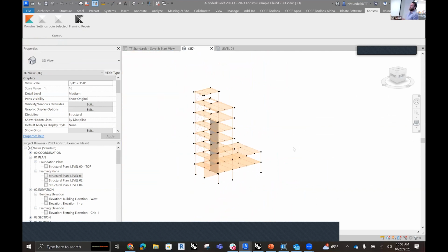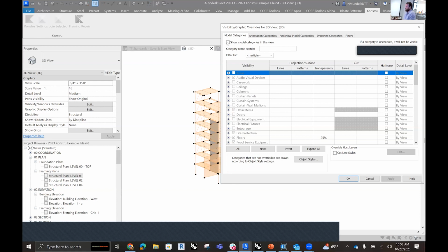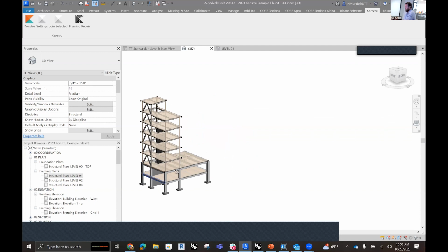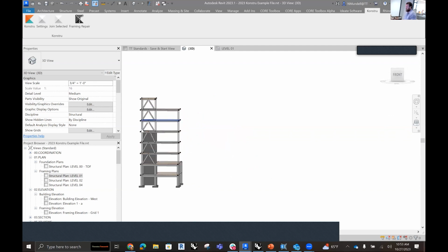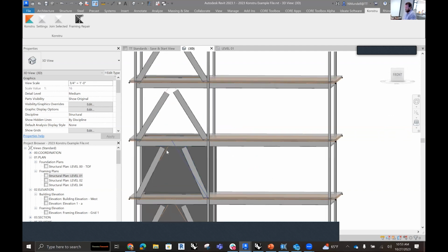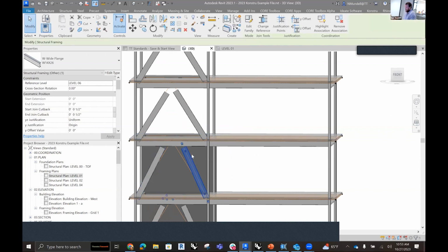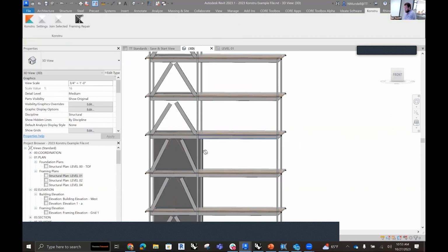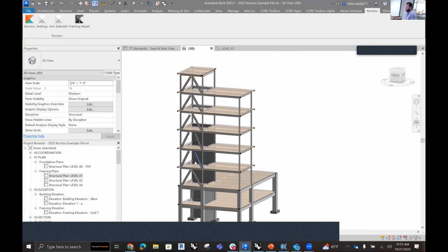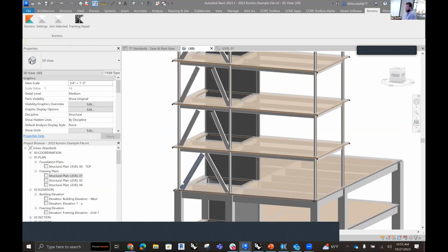So at this point, this model is in a good state for analysis, in particular, obviously, the analytical position of the objects. Just to be clear, we did not adjust at all the physical position of those objects. So whilst our analytical braces are now connected to the center, we did not move at all the physical position of the objects. It's entirely possible to do so if we wanted to. So let's try an example where we use a selection-based upload.